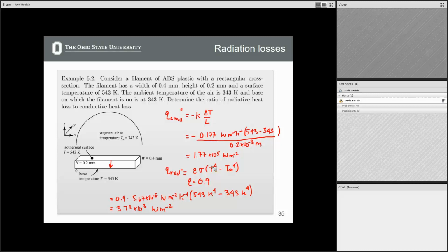So I don't see anyone report any discussion about Marangoni convection happening in material extrusion. I think it's safe to say it doesn't happen. The viscosity of polymers above the glass transition temperature is considerably higher than the viscosity of molten metals. Molten metals flow like water, essentially. They're very, very low viscosity. So I haven't seen any report of this, so I'm going to safely assume that. It may not be too satisfying, but that's really the reality of the modeling of these types of processes.